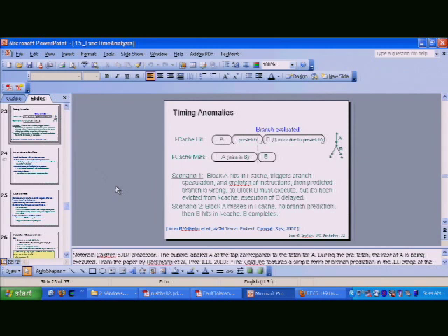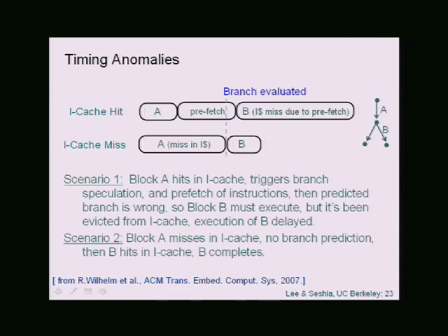All right, so before I get started with fault tolerance, I want to revisit this slide from last Thursday's lecture. Remember, we talked about timing anomalies, and there was a question about why there wasn't any prefetching in this case. So I went back and tried to find documentation on this processor. This particular scenario is not described completely in all detail, but from what I can make out, here's what happened. The processor was a Motorola Coldfire 5307 processor. All you need to know about this is, for this anomaly, the structure of the pipeline is relevant.